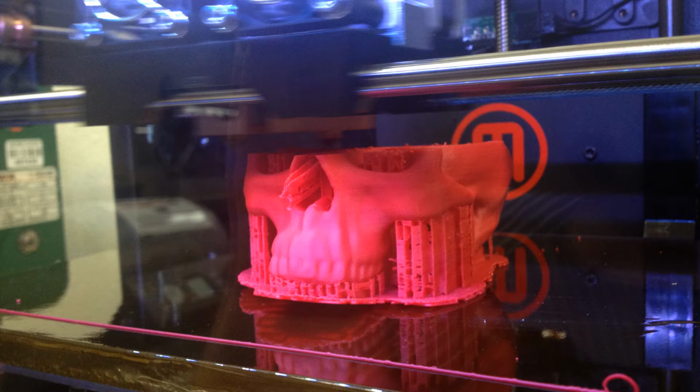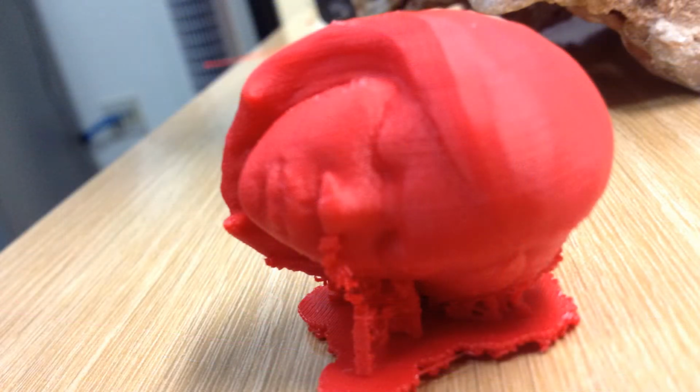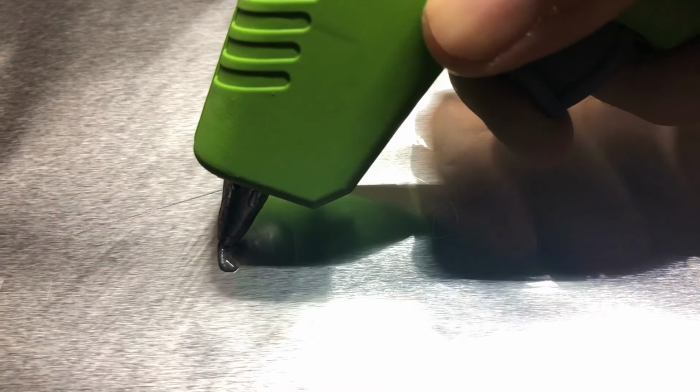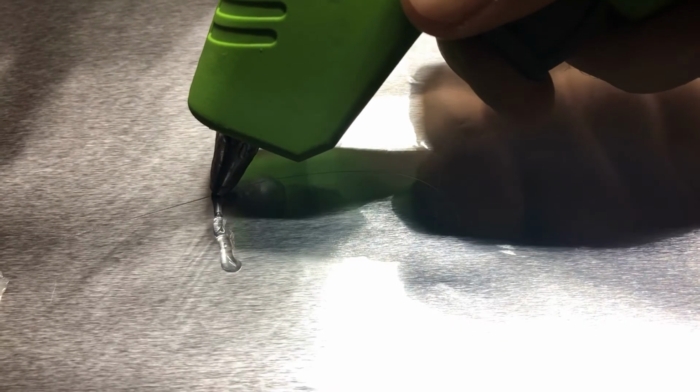Fused deposition modeling, or FDM, draws many layers in thin lines of liquid or viscous material onto flat surfaces. Molten plastic is most often used, but other FDM materials for specialized printers can include concrete, carbon fiber, and even chocolate. This printing process is often inexpensive but slow, and the results produce durable but low-resolution models. FDM printing could be simulated at home with a hot glue gun, a steady hand, and a lot of patience.